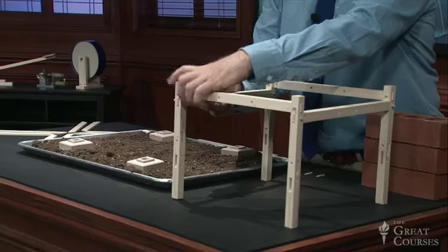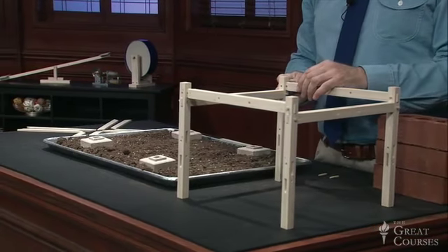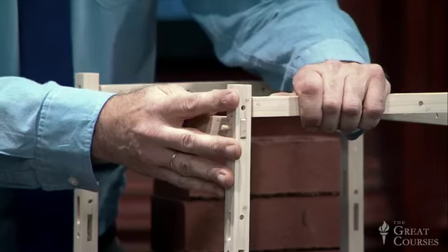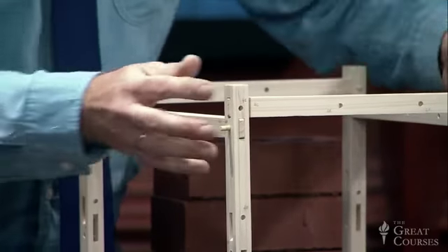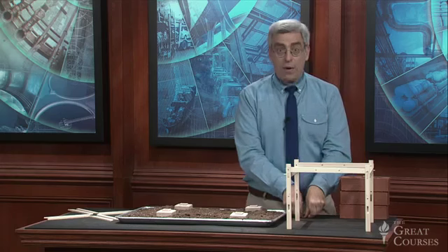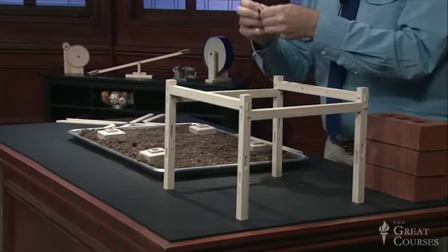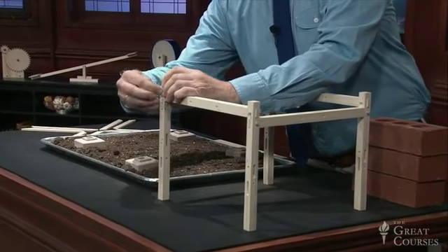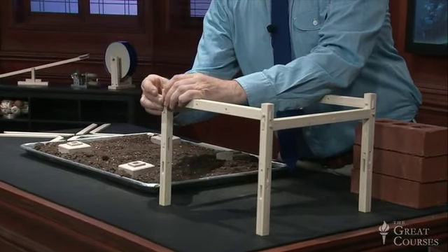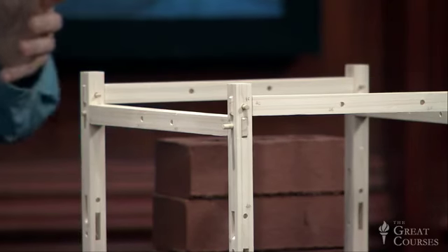So here, a tenon is inserted into a mortise at either end of the frame that I'm adding to the structure. We plug them into place, and then we secure them in position by driving a wooden peg through a hole that connects the mortise and the tenon rigidly together.